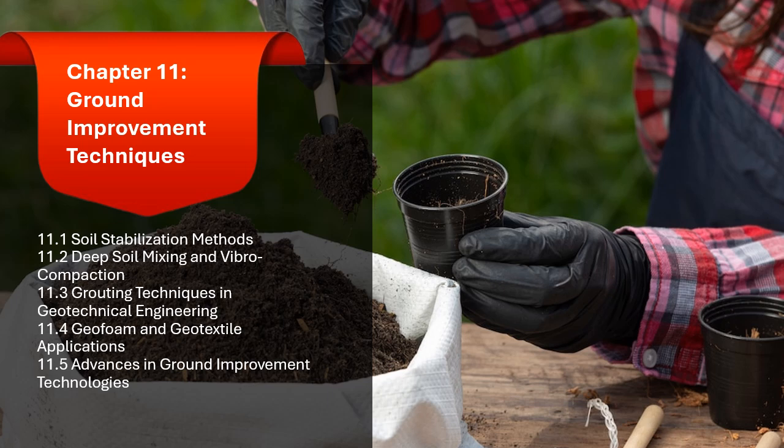After grouting, quality control tests such as borehole inspection, permeability tests, and compressive strength tests may be conducted to confirm the improvement in soil properties.